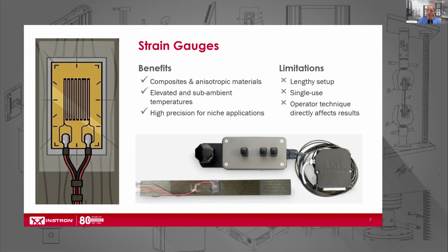A common customer complaint I hear with strain gauges is setup time. Each gauge needs to be adhered individually. Certain adhesives, especially for those non-ambient tests, may have cure times of a few hours, so it's certainly not ideal for a high throughput lab environment. Also, keep in mind these are consumable and need to be disposed of after the test is complete.